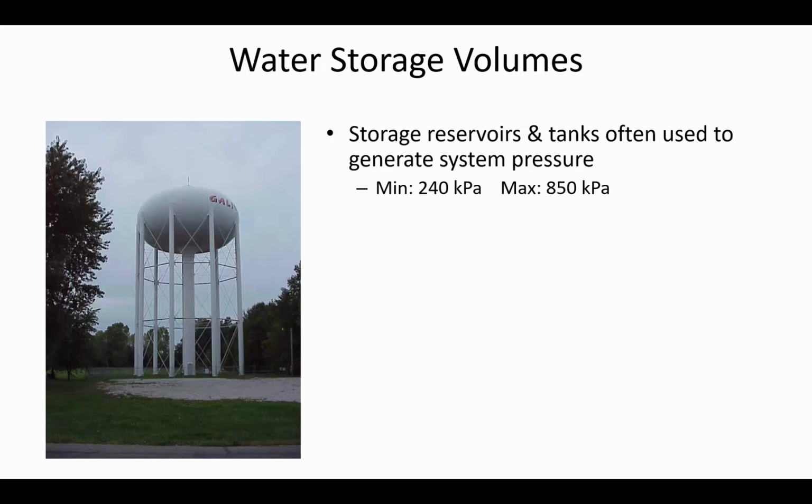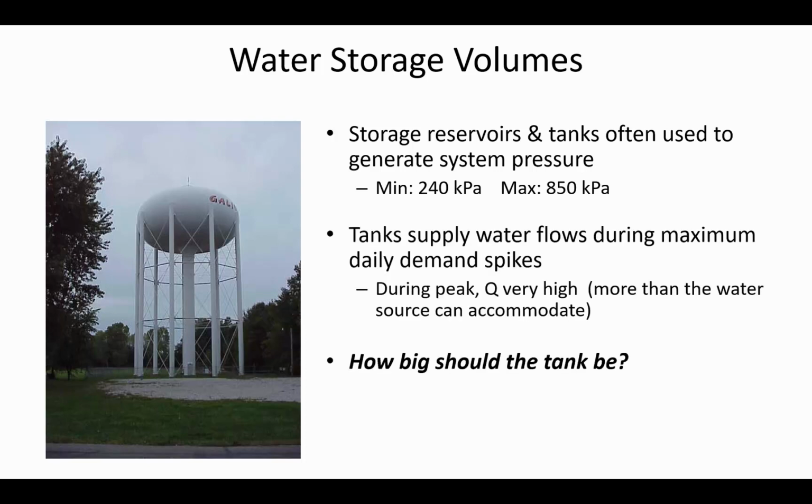But that's not very often. Most of the time the demands will be much lower, and so we're going to be closer to this maximum pressure. And the maximum pressure is going to be observed during periods of low flow or no flow, like the static condition at night. So we want to pick a reservoir location that satisfies both of those constraints.